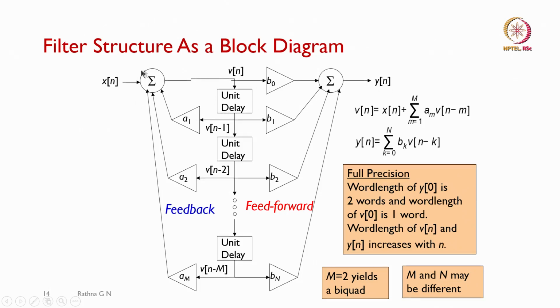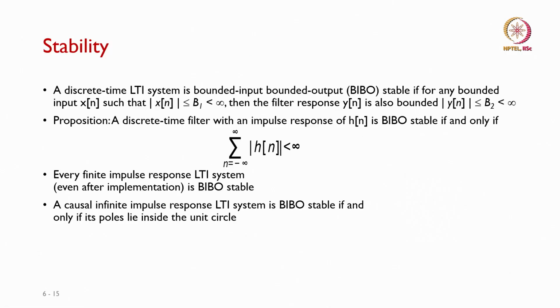So, the critical path, what we call it, is overflow or underflow, because here all of them are negative, we may underflow in this case, and if all of them are positive, we may overflow also. So, these are the two critical nodes, what we call it. One has to take care that the summation is not going to overflow or underflow at these 2 points. From one single critical node we have bifurcated into 2 critical nodes, but as you can see, the delay units have come down by 2 compared to the previous direct form structure representation. So, that is the advantage.